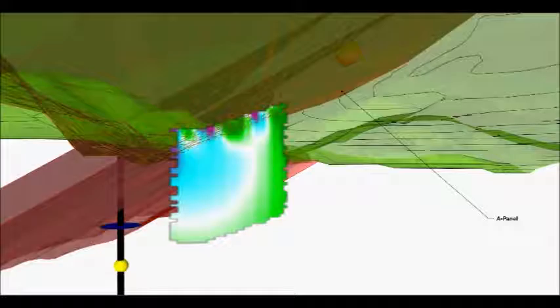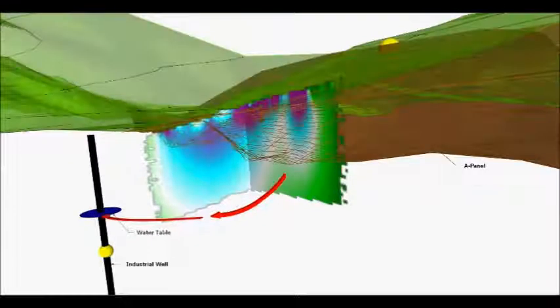The green color shows preferential paths of electric current, which imply preferential paths of groundwater. Red arrows have been added to highlight these paths. The large arrow indicates the majority of electric current flow from the east hillside down into the Wells Formation. The small arrow identifies flow from the runoff recharge area to the underlying Wells Formation. Due to pumping from the industrial well and its capture zone, water flows toward the industrial well. The red X identifies an area directly beneath the utility corridor, which is unrelated to meteoric flow paths.